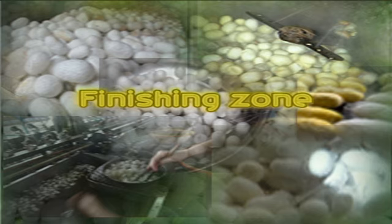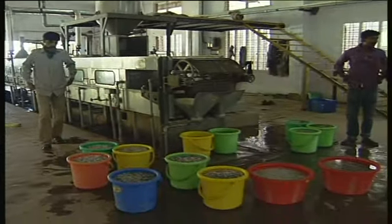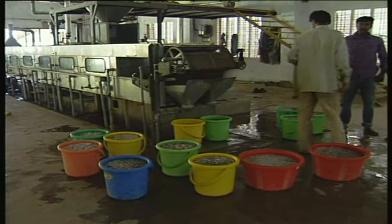The temperature is adjusted such that it is gradually reduced from the steaming zone about 100 degrees centigrade to a low temperature of 40 degrees centigrade at the finishing zone. Number 6. Finishing zone. This is the last part of the cocoon boiling machine, where the cocoons are treated at a temperature of 40 degrees centigrade to 45 degrees centigrade for about 1.5 to 2 minutes.